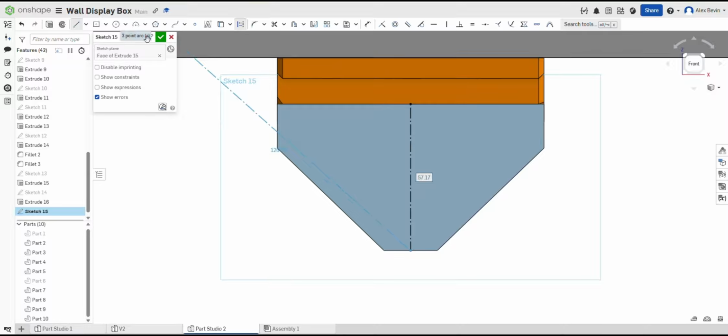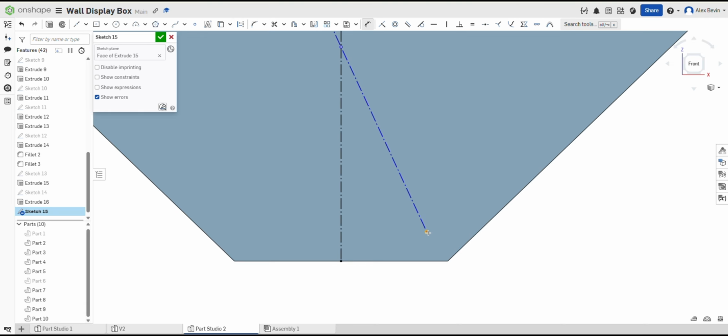Section B. Add the wall mounting holes, countersink. Next, we need the mounting holes because this bottom cleat is what actually fixes to the wall. The goal is simple. The screw heads sit flush, nothing sticks out, and it mounts cleanly. I'm going to use the hole tool for this. Set it to metric and choose countersink. Now select the sketch points.